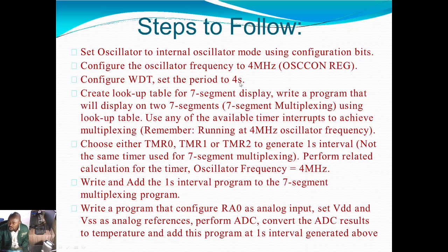The watchdog timer is used basically in microcontroller systems to prevent the system from being stuck forever. Let's say something is wrong, the program is no longer running the way it's supposed to, and it is stuck in a certain section. It can be stuck in that section for 4 seconds, and if it gets stuck for more than 4 seconds, then the system will automatically reset. It doesn't mean it will solve that problem, but at least the system will still be functional.